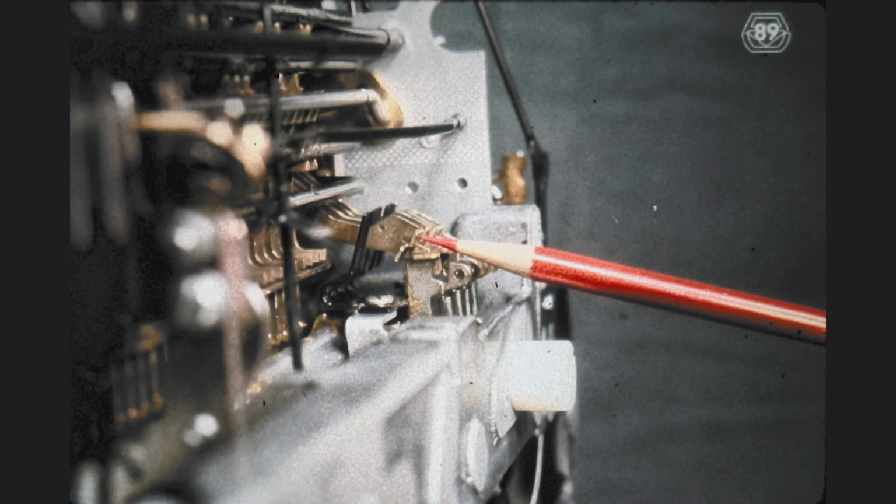The vertical position of all of the other operational keylever pawls is adjustable by either a horseshoe adjustment or an eccentric, depending on the level of the machine. The clearance between the operational interposers and the keylever pawls for the backspace and for the carrier return engagement mechanisms should be approximately 0.6 mm. The smallest clearance is that of the indicated spacebar keylever pawl and the spacebar interposer. It should measure only 1/4 of 1 mm.